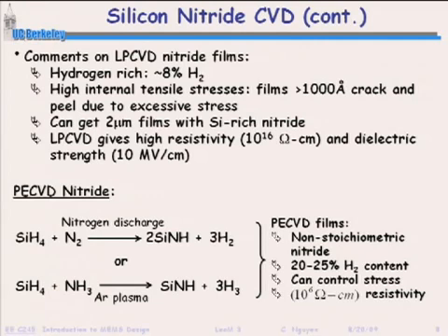The way that foundries are able to get repeatable silicon and even repeatable MEMS now is they dedicate a tool to doing one and only one thing. So it's always dialed in. At this university and at pretty much all universities across the nation and the world, no tool is dedicated to one purpose because we simply don't have the space and the money to do that sort of thing. So some of the etchers upstairs, some of the PECVD systems, they're depositing lots of things over lots of different substrates. And tiny changes in contamination or conditions can cause drastic changes in how those tools perform.